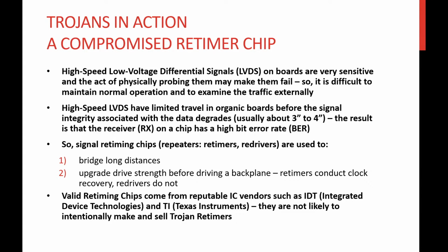A clock edge may be viewed to occur at time 0 at the source of the clock signal, but as the clock propagates across a distance, the clock signal gains delay and the clock edge moves relative to the time 0 edge. At a far enough distance, the edge may move a whole clock period, and so data at that location would be one clock cycle delayed from data at the time 0 point.